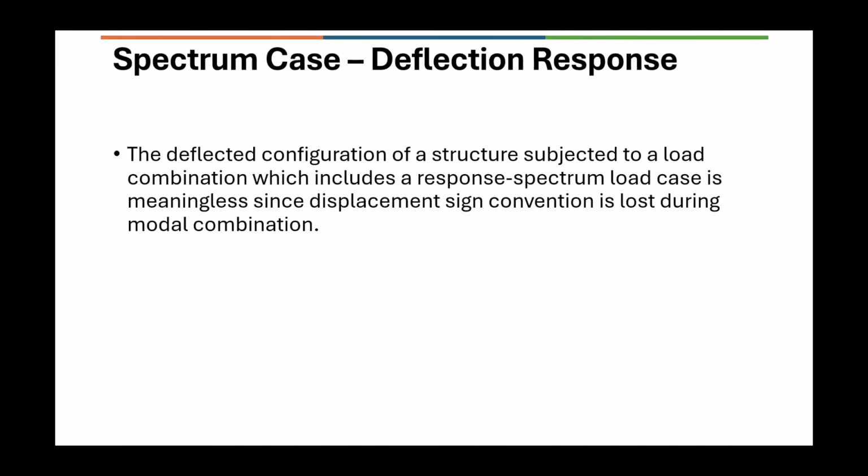So in some situations, when you want to check for these serviceability criteria, then the best way is to convert the response spectrum cases to linear static cases and check for this.